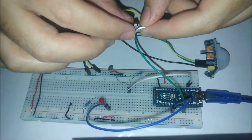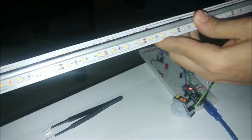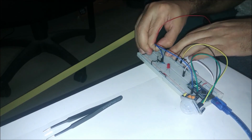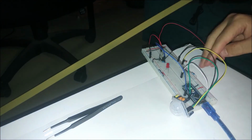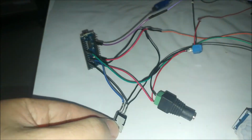Let's add a transistor to the circuit to be able to use a 12 volt LED. The gate takes the digital pin output. Drain takes the negative terminal of the LED and source to ground. And it's working.